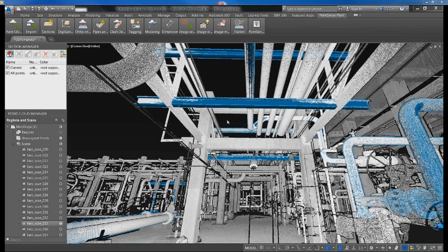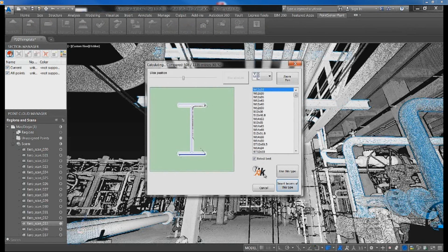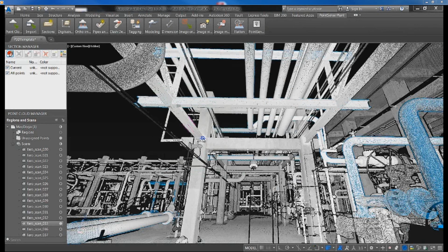So we're going to do Detect Type again. This is actually a different size, and if you're ever not sure, just do a Detect and it'll tell you what it is. There's a very nice overlay showing the cloud data with the actual pattern we're using, and then I'm just going to extend it, click any point along that plane, and it'll extend the steel to that spot.